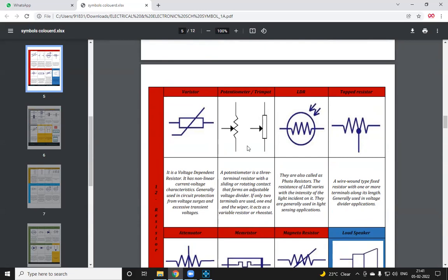See, the format is not specifically defined. It should have proper information in the naming convention, so that by reading the name, you should understand what the component is, what the value is, what the package is. Don't miss what I told you. By reading the component name, it should be easily understandable: the name, the value, the package, the wattage. That's why I explained it in DigiKey.